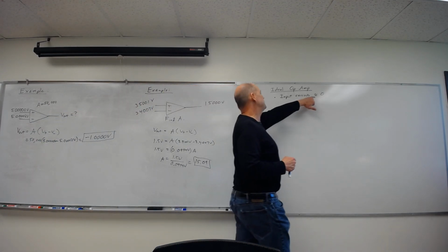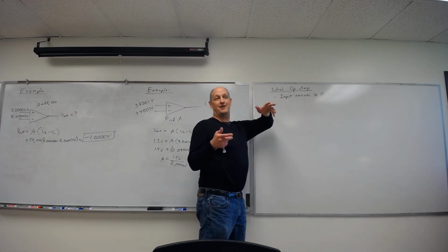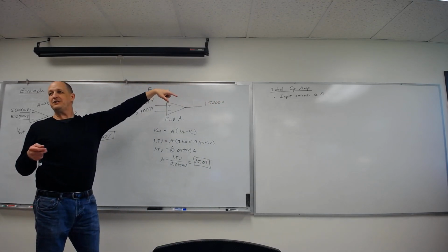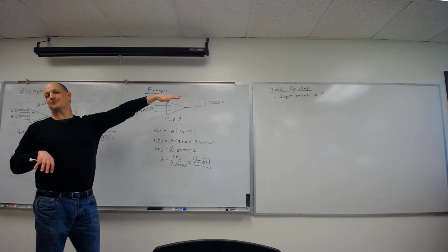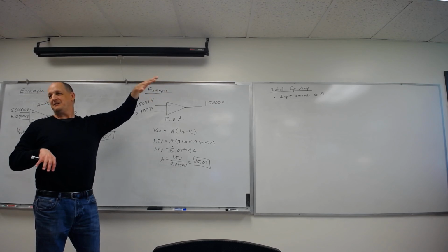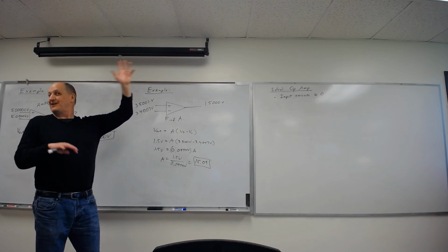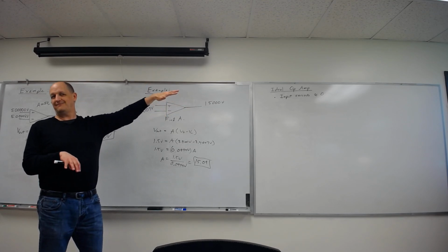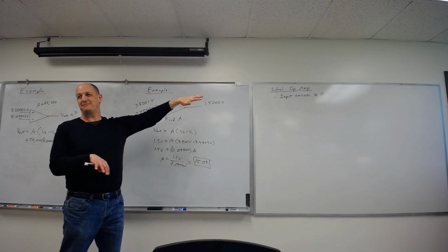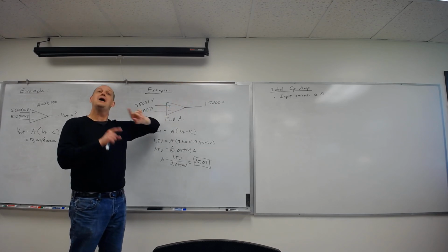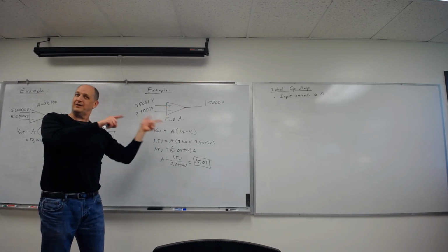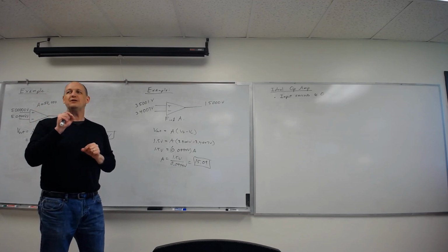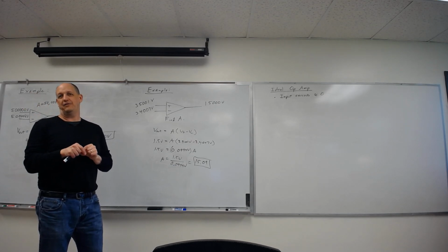Remember how we did the same assumption for my transistors for the input current? This is even more true. My electrical engineers will scoff at assuming 0 input current for the transistors because it's actually only like 100 times smaller than the current flowing through. No, in this case, it's going to be like tens or hundreds of thousands of times smaller. So they all go, yep, input 0. Same thing, if input's really 0, you don't get anything out. But your inputs will probably be down in the nanoamps, maybe low enough you can't even measure them in lab with our equipment.